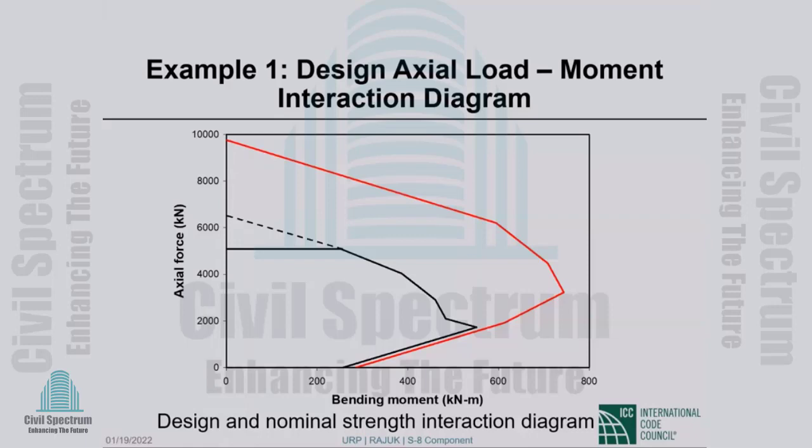Okay. So which one is recommended in circular column for high seismic zone, spiral or circular ties? Spiral gives you better behavior than circular ties for sure. Which one is recommended? I do not know. That depends essentially on pricing. Yeah, I do not know.